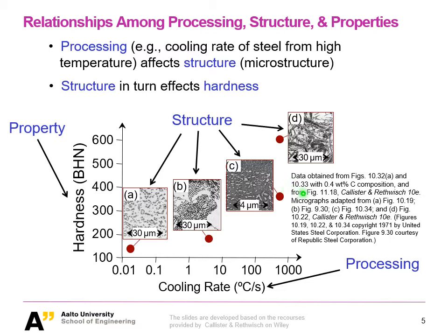If you compare these two, I think I asked you during the course, what is the difference between tempered martensite and spheroidite? They're both ferrite with a certain cementite in a rather particle form, rather than a laminar form as in pearlite.